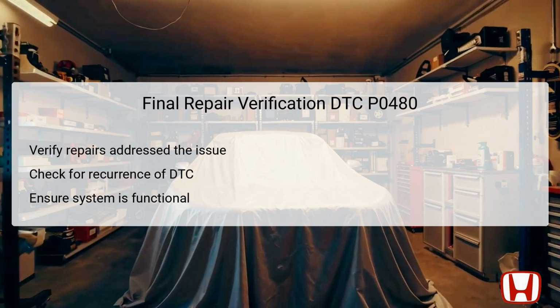Conduct functional tests of the radiator fan to ensure it operates correctly under various conditions. Check for any recurrence of DTC P0480, ensuring the system operates without error after repairs. Successful verification concludes the troubleshooting process, proving effective rectification of the RFC system's malfunction.